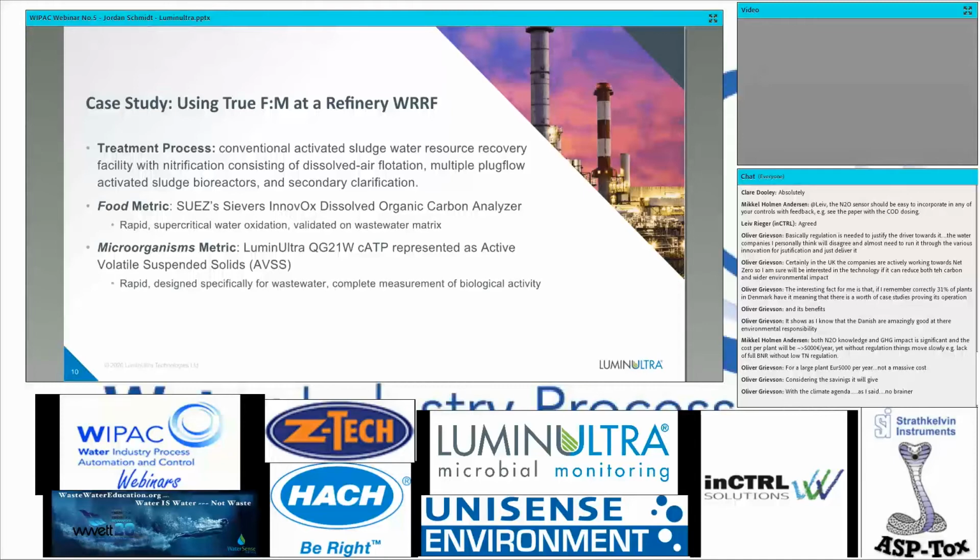Then the microorganism metric used the LuminUltra QG21W ATP test, represented as active volatile suspended solids. So that's that unit conversion from nanograms to milligrams. This is a rapid test designed for wastewater specifically, thus the W in the name, and it's a complete measurement of biological activity.